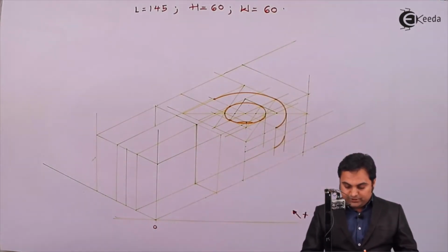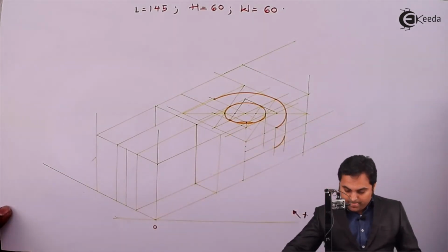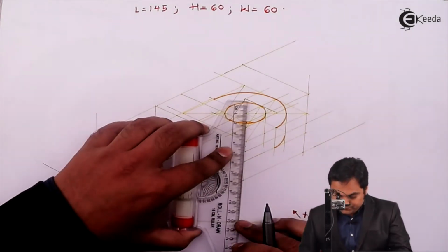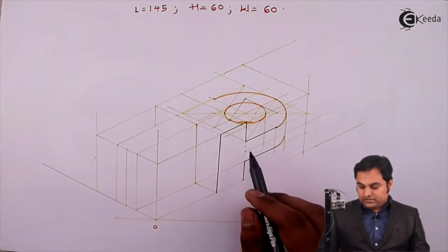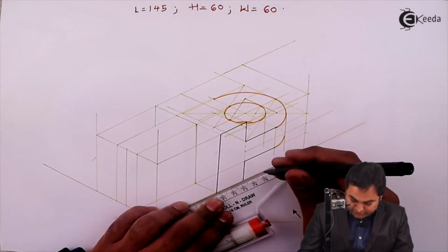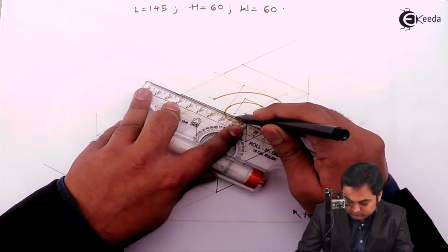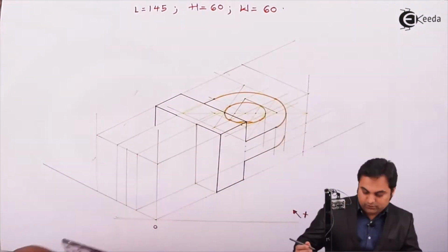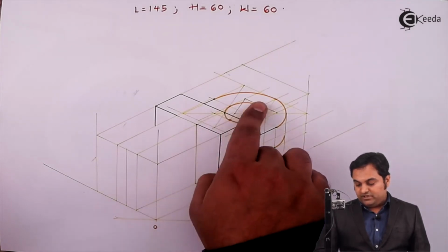Next, once I have drawn this portion, in that case, I can draw the surface here because as per the priority, this surface will be visible first to avoid any confusion here. Because after drawing this surface, then only I will make the circle and semicircle dark so that we can understand which part is visible and which is not. So this procedure needs to be followed. That is first making this surface dark. Now once I have made this surface dark, now I can easily see that the portion which is intersecting, this should not be made dark, but the remaining things will be dark.